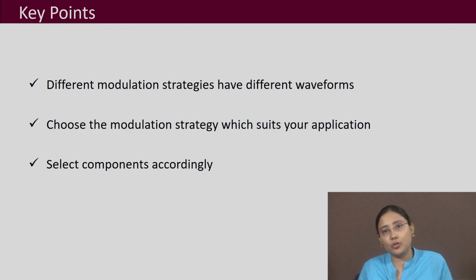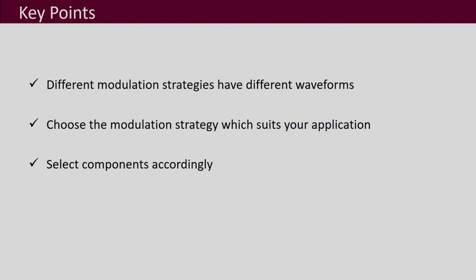With different modulation strategies the waveforms are different, and accordingly the choice of components, the inductor, capacitor, and switches, may all become different. So, before choosing your components, you should fix your modulation strategy.